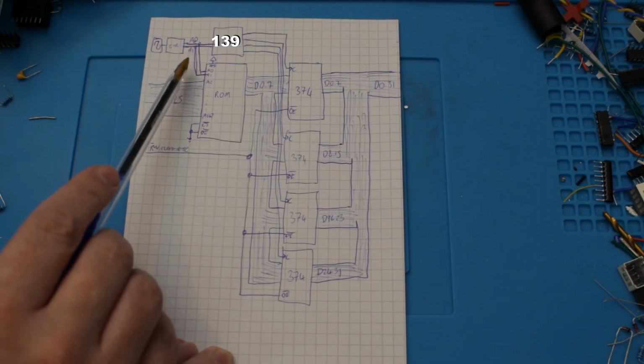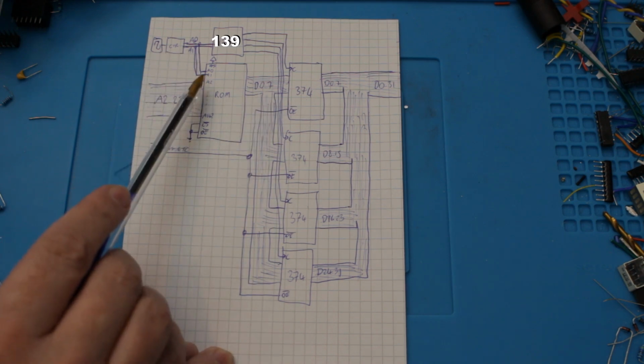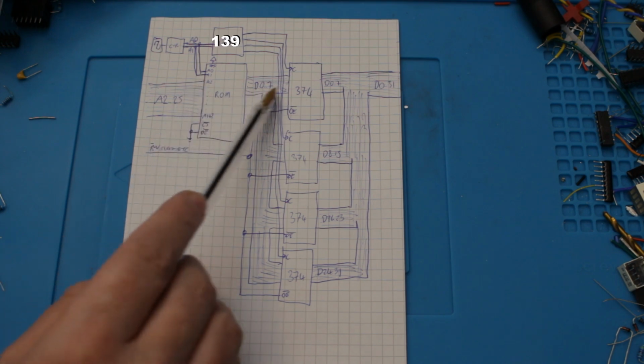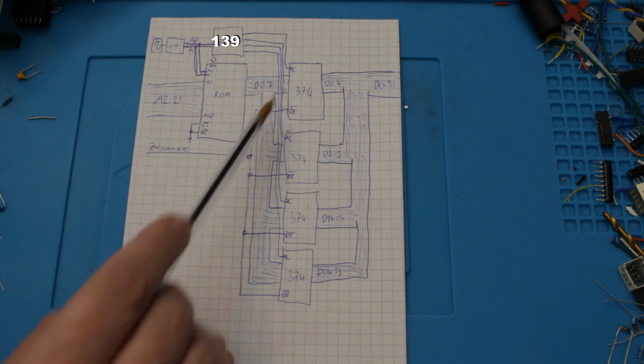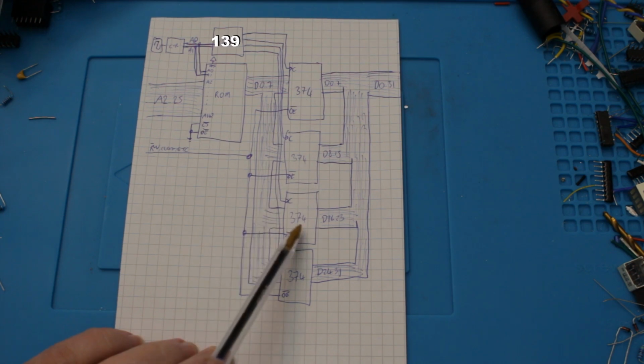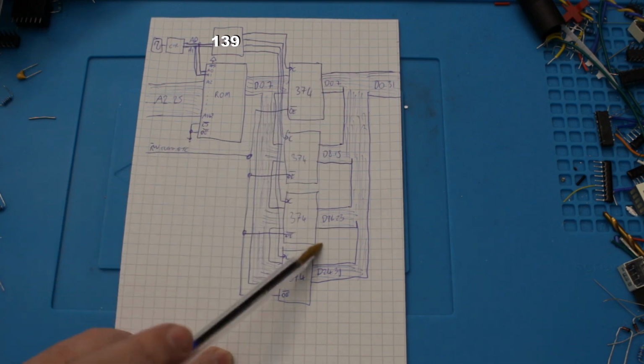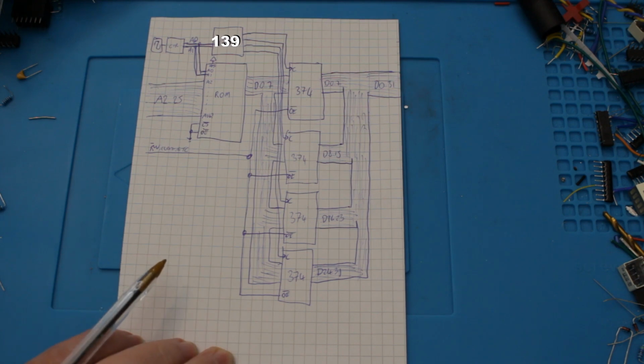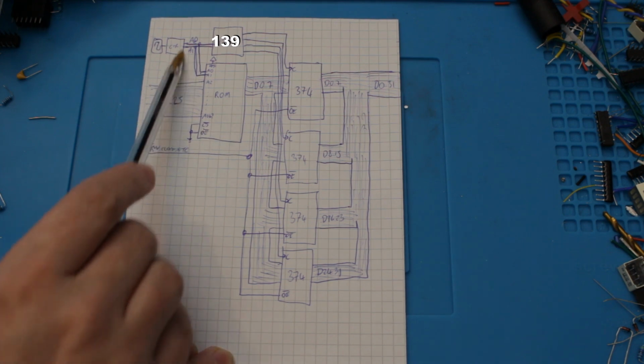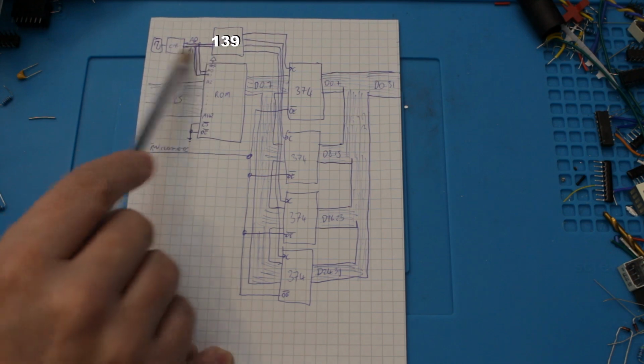we actually need to hit this ROM 4 times per bus cycle and capture the 8 bits from the ROM into separate 8-bit D flip-flops here. And then when we have all of the data in all of the D flip-flops, they then feed the relevant parts of the CPU bus. It is a bit more complicated. The mechanics here are a little trickier.